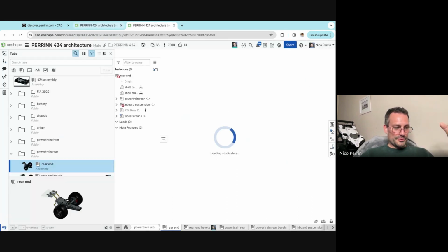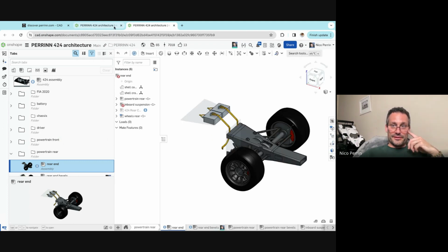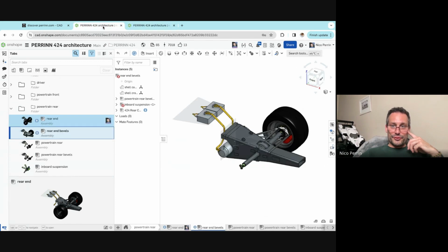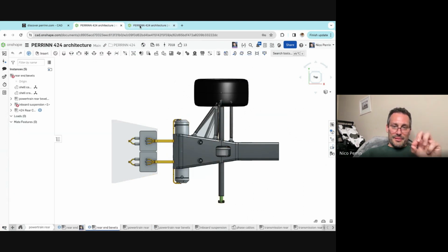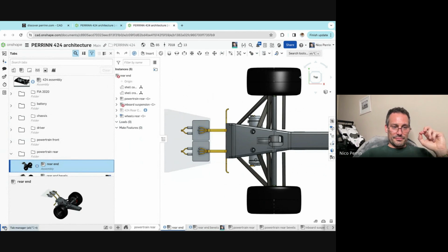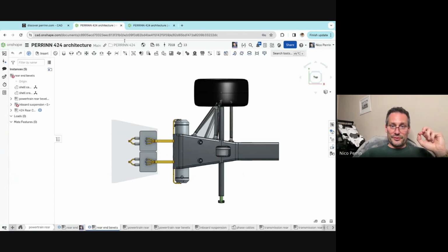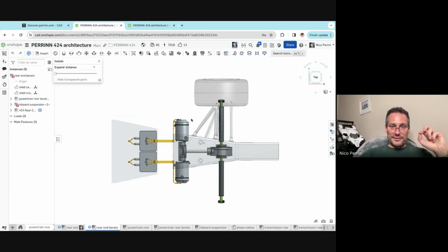This is a new development that happened 6 months ago, and the one that we're going to build is this one. So if I show you the differences, right. But I'm opening this so I can answer your question as well. So just give me a second. So here you can see the location of the motors is different. If I show you the powertrain itself, you can see here we had two electric motors connected to basically a mini gearbox made of bevel gears, 90 degree gears, with a lay shaft, and then another box with bevel gear to the final drive.